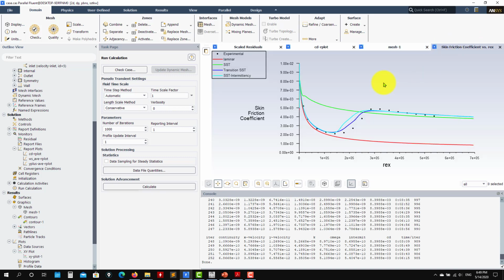So it can be elusive and difficult to resolve. And one thing: use transition modeling only if you know that the physics you are solving requires these kinds of models, because it can be really difficult to get the solution and requires verifying measures.